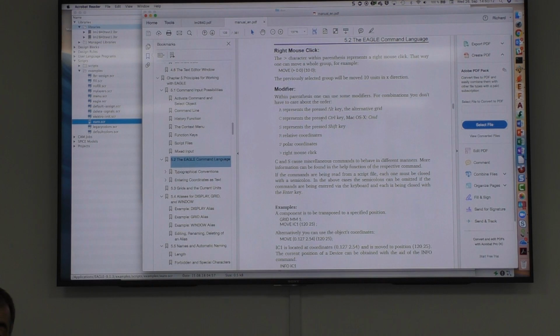So there are a lot of examples in the manual. You have to look into the help for the commands. There you find all the options. We have seen the pin command. I write pin in single quotes the name, and then I use middle, clock, IO, whatever. I have all these options and can write it down. So that's what we do in the script file.